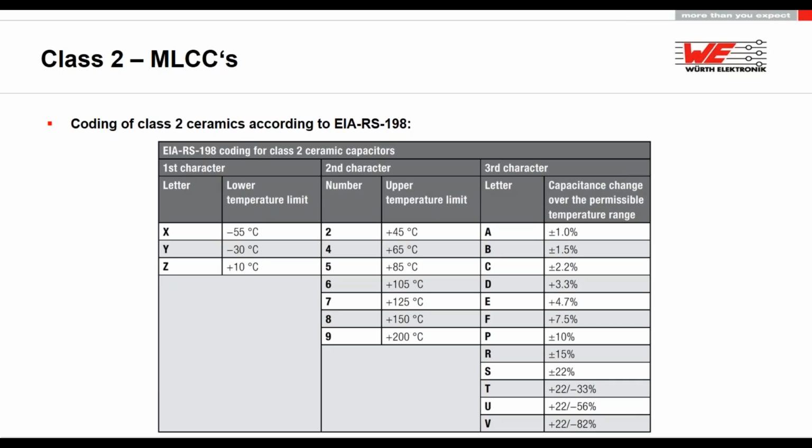And due to the fact that not everybody uses the same basic powder for ceramics, temperature behavior at different temperature levels can be different. So if it's very important to have stable values against temperature, you have to consider asking the manufacturer for curves for this particular temperature behavior.